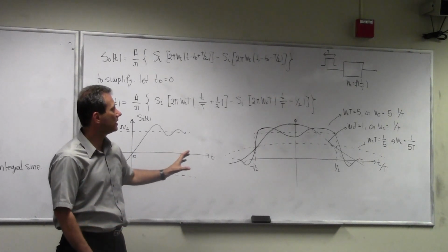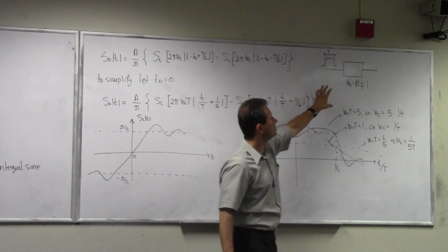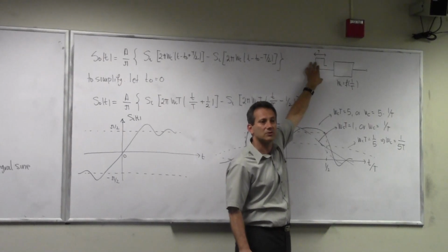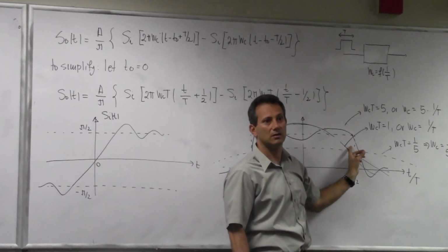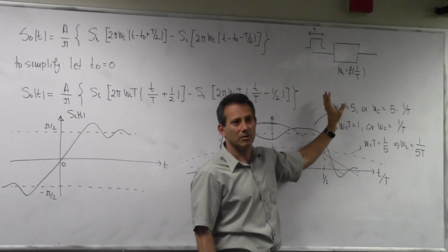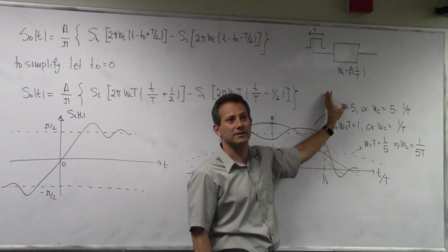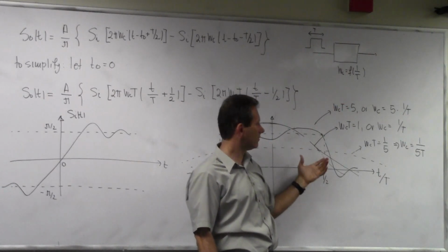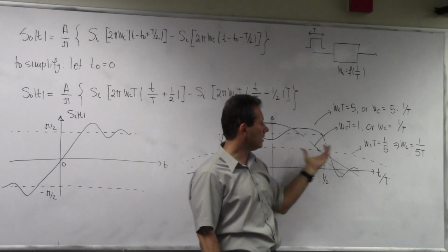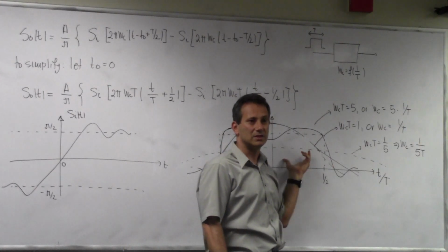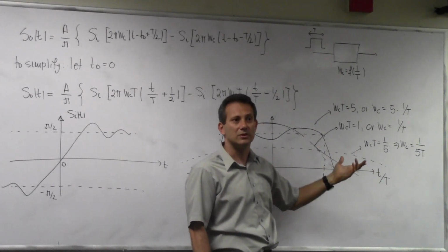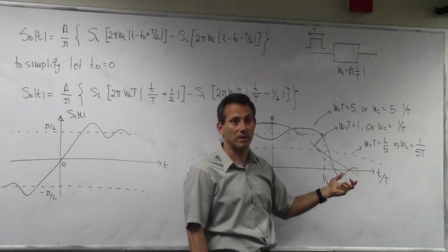If you make an attempt to signal over a band-limited channel without judiciously choosing your symbols or the waveforms that you're sending, you'll end up interfering with yourself. And no amount of power that you pump into the system will fix that. Because whatever increases the energy of your signal during the reception period will increase the interference that this signal creates to adjacent reception periods. Therefore, your signal to interference ratio stays the same regardless of your power.